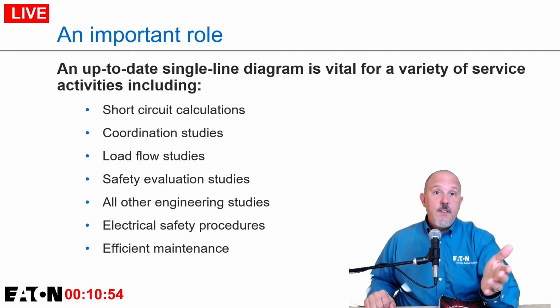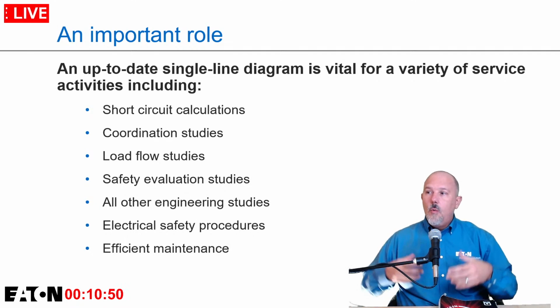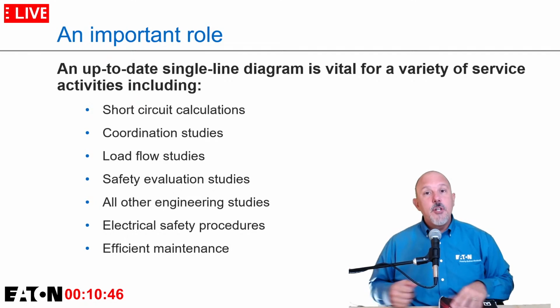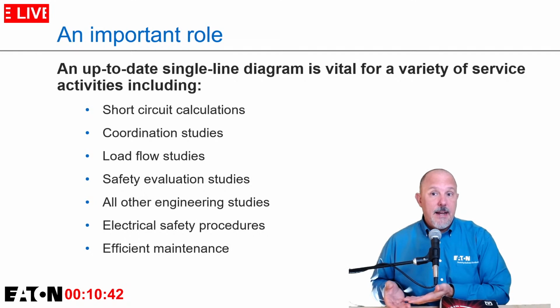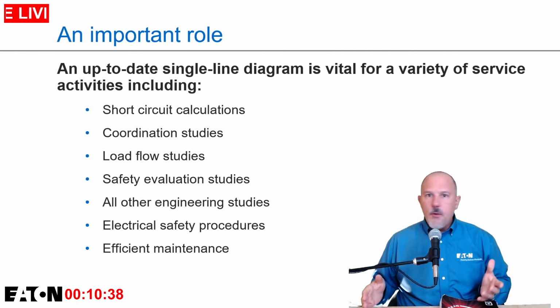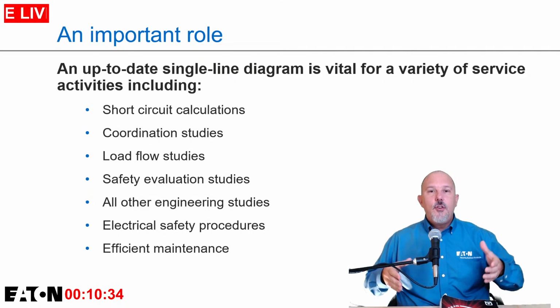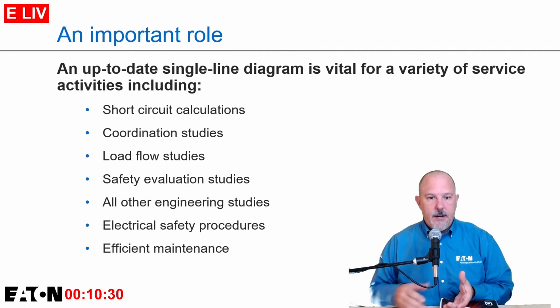I throw safety evaluations in there, because safety is a critical role to know what I need to turn on and off, or hopefully turn off, to establish an electrically safe working condition. I might rely on a single line diagram to let me know what's upstream. Any of your engineering studies are going to start with a single line diagram. Your safety procedures are going to probably start with a single line diagram.